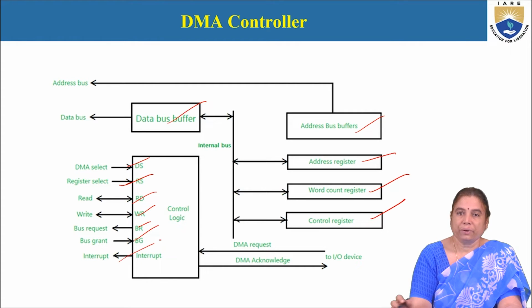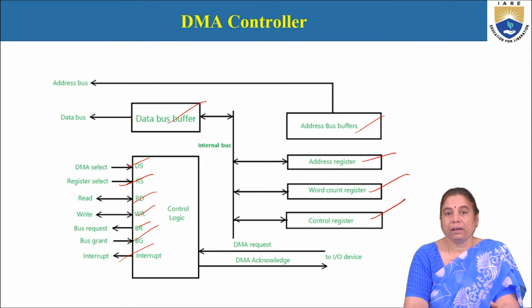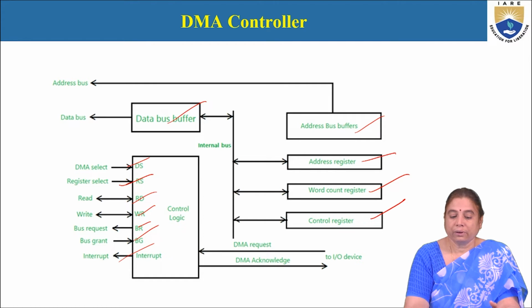And in case of interrupt initiated IO, the peripheral that requires the input-output operation can raise the interrupt so that the DMA controller can identify that the peripheral requires the IO service, which can in turn issue the bus request to the CPU so that it can grab the attention of the CPU and be involved in the direct IO data transfer between peripheral devices and the memory.